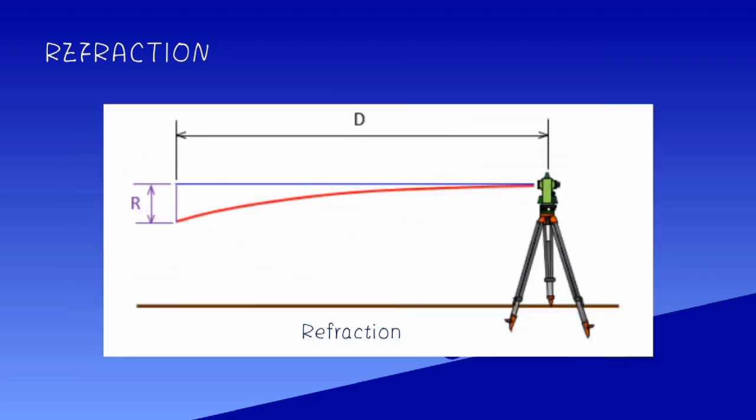The amount the line of sight refracts from the straight line is not linear. At 200 feet, it is not twice the refraction at 100 feet. Over short distances, the atmosphere density distribution is relatively uniform. At longer distances, that is probably not true.